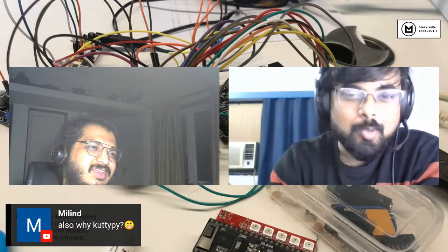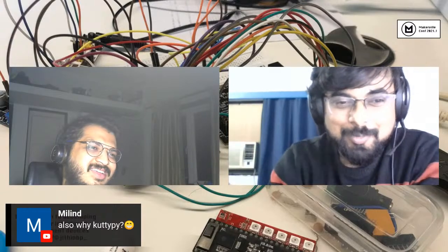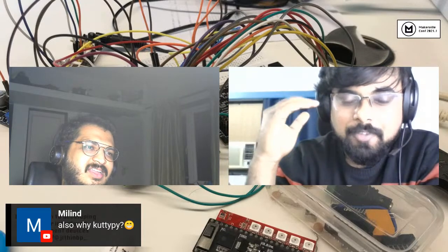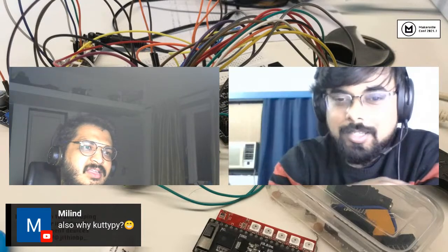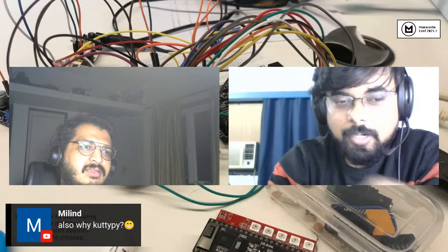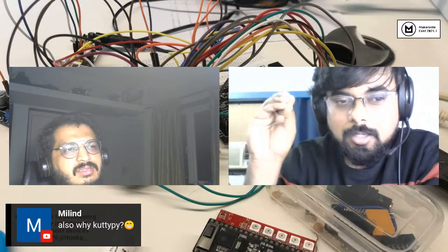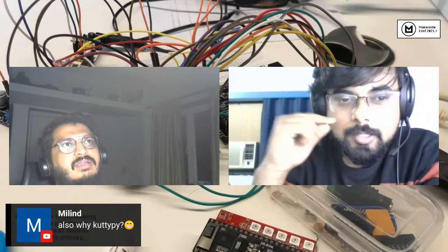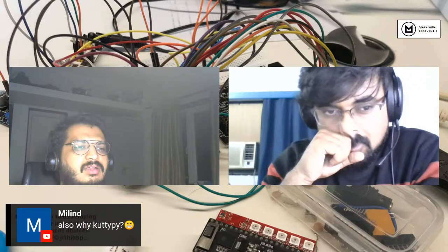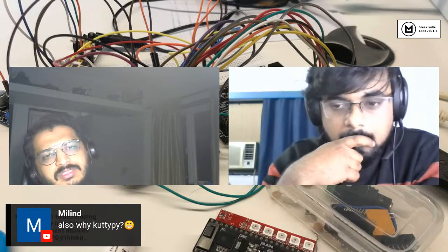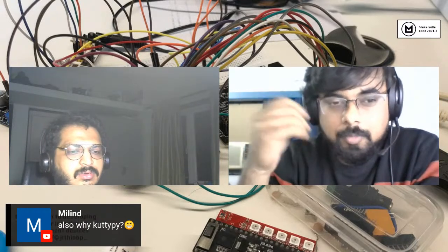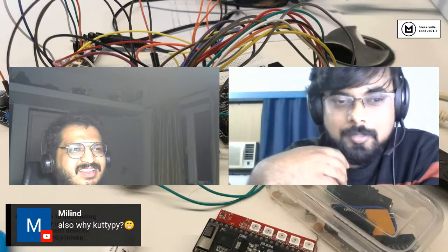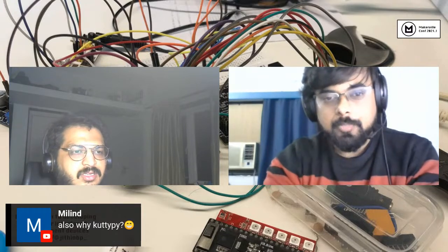At the base level, it's only bumping values from here to there. Everything else, all the sensors, visualization, protocols, is on the Python side. On the hardware side, there's only like 2-3 function calls. Python will handle every specific I2C protocol for each sensor. All that is in Python. You don't need to touch the hardware to change that. So it's heavy on the CPU side, like on the laptop, because that's where Python development is easier. Yeah, so I wouldn't hard code anything onto a small processor. Makes sense. Nice.